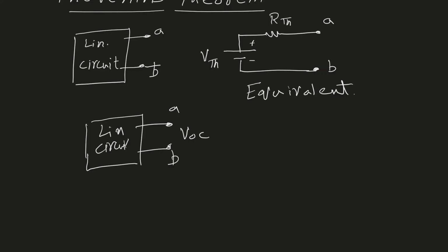All right, so now if this is the voltage that the circuit produces when it is open circuited, if we now consider our Thevenin circuit, and if we keep this open as well, because we want to ensure that the two circuits are equivalent, then the voltage at the output in this case will be VTH. So now comparing the two circuits, left and right,